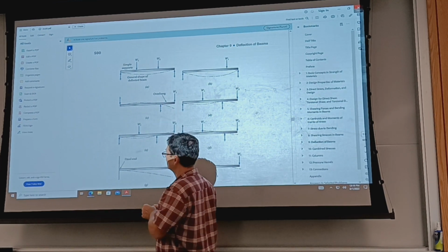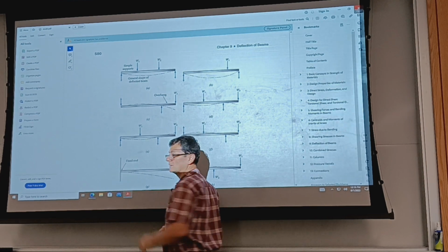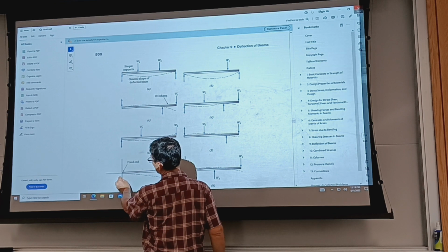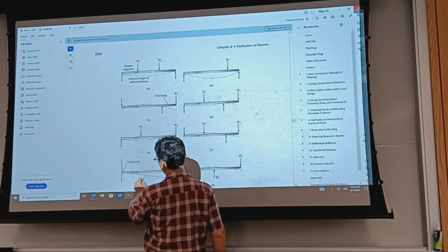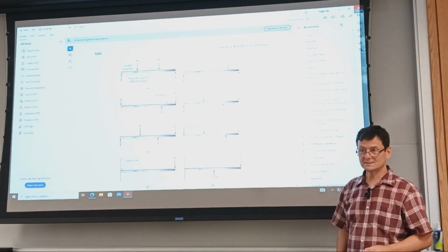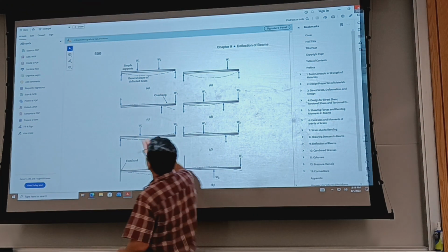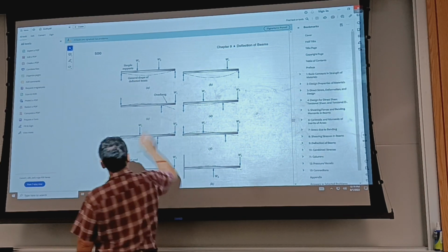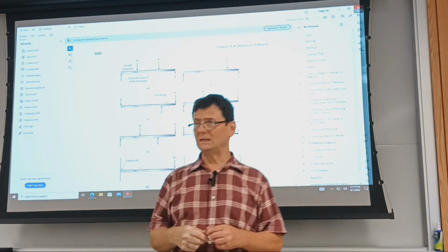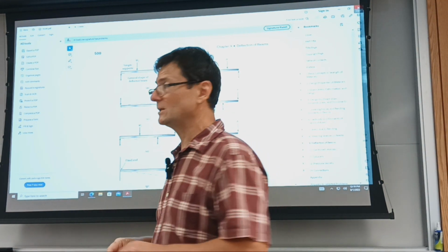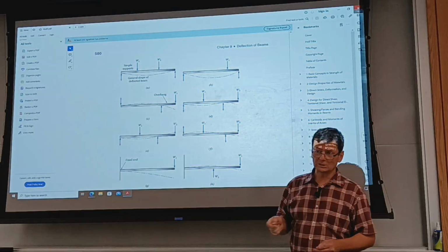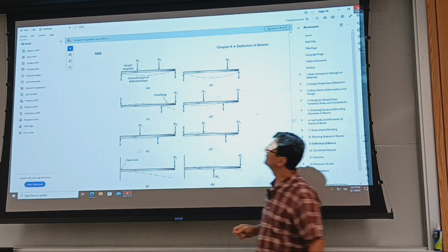If you have a cantilever, because of the way the support acts, the beam right at the support has a 0 slope, and as you move away, the slope increases in the negative sense. Does it make sense? So it matters. If I have supports, then the deflection is 0. Here, both the slope and deflection are 0. And these are important because as we integrate, we need to reconcile some constants of integration. And how do you do that? By taking into account what are called initial conditions or boundary conditions, okay?